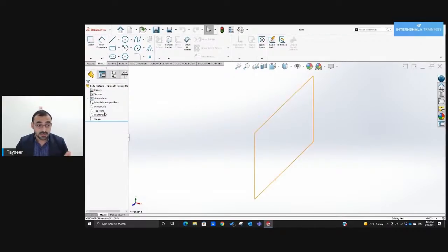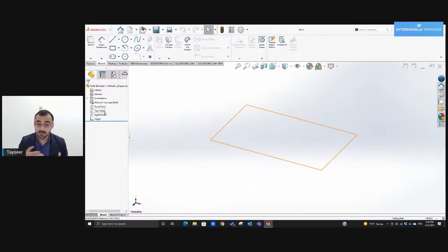For now, I'm going to select a plane and then do a sketch and then do a feature. Just like we did in our mental exercise, when you're building 3D models, we keep going on the same cycle of sketch, feature, sketch, feature, sketch, feature. So let's go ahead and start with a sketch. I'm going to select the top plane for this, click on it, and then click on this little command here that says sketch.